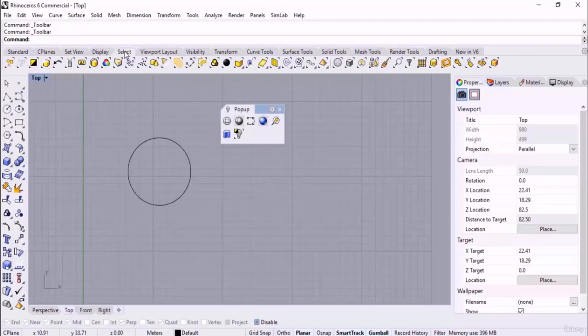to my pop-up. Then in select last created objects, click and drag while holding down Ctrl and then release. And then in Array Tools, Polar Array, hold down Ctrl, click and drag and then release for adding the tool to the pop-up dockable window.